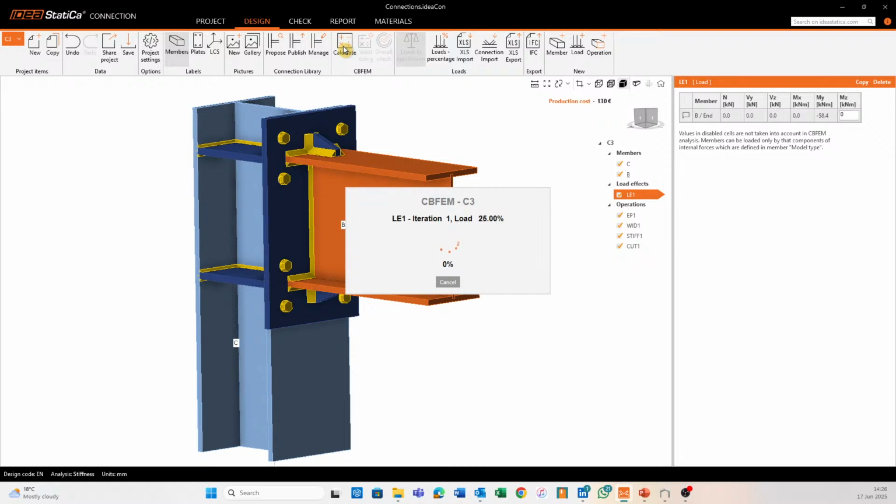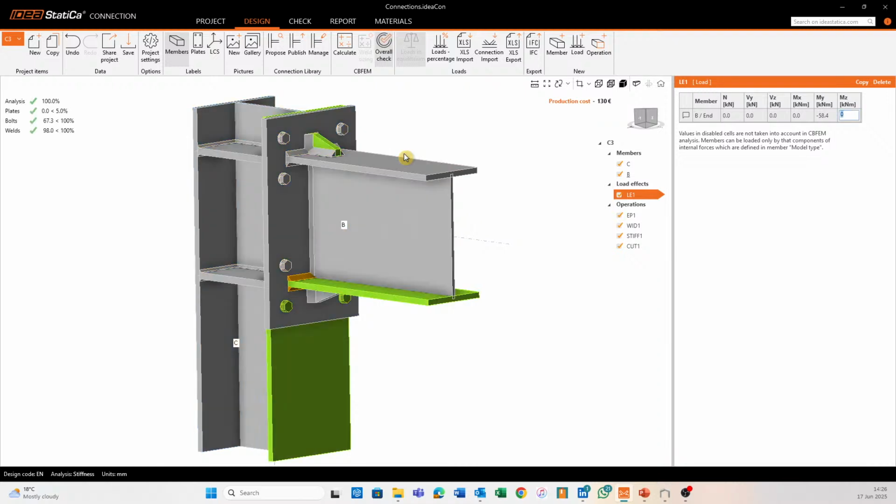You have to go back and forth, so multiple iterations, to get all the values to remain constant. You need to run through a few iterations to check that all of those values get as close as possible to each other and that they don't change. Then you know, okay, cool. I have a successful stiffness analysis and I've successfully incorporated that into my global model.